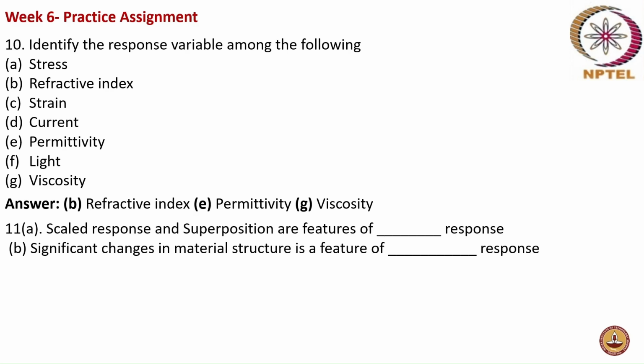For example, one set of voltage you're applying and then another set of voltage, what will be the sum? If you apply 1 volt and 2 volts, then when you apply 3 volts, you can just add the responses of 1 and 2 volts and get the response of the 3 volts application.